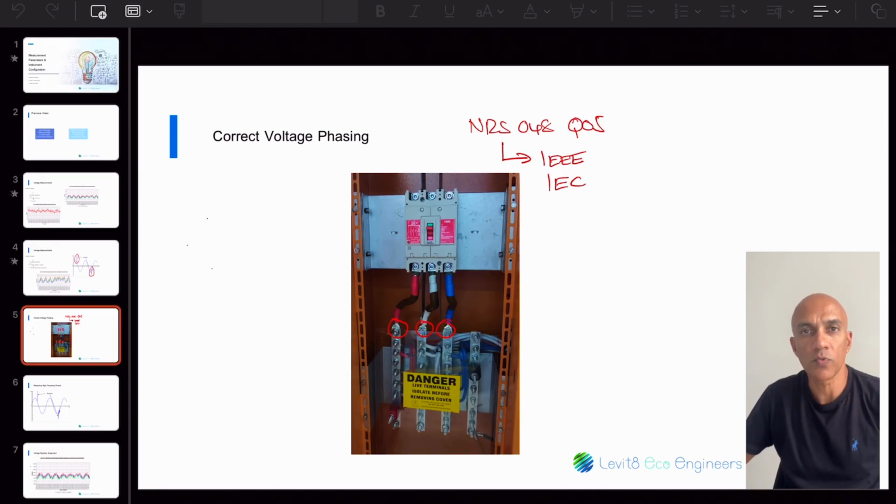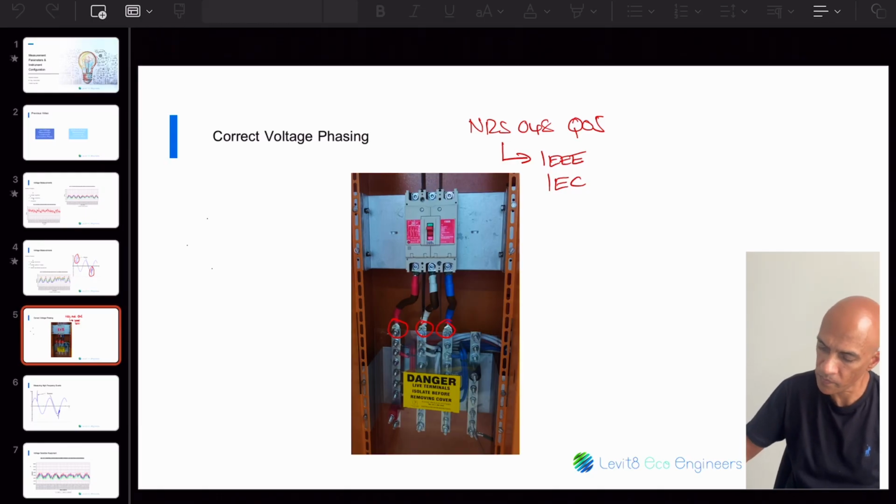You may also just want to measure voltage for specific problems, such as continuous undervoltage or overvoltage. In my recent experience at home, I had appliances not performing properly, fans running slow, microwave oven not heating. And when I tested the voltage, I found that my house was getting 180 or 190 volts on a 230 volt system. You may have customers where they experience similar issues at their places of business.